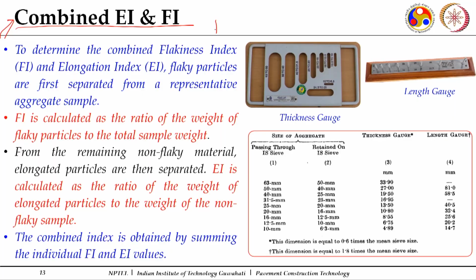That gives you the flakiness index, which is the weight of flaky particles divided by the total aggregates weight.